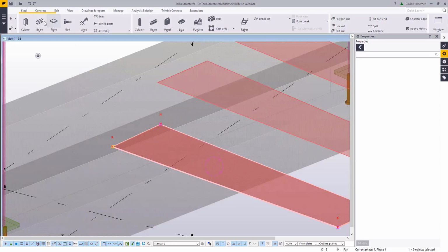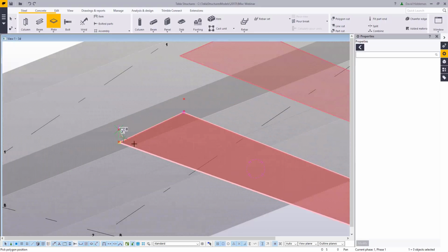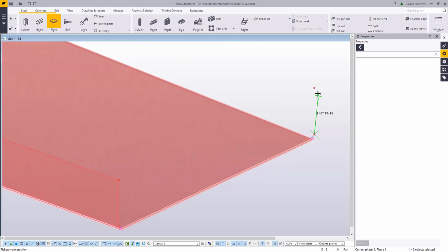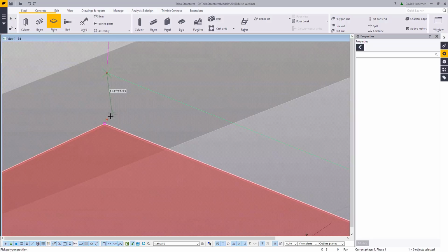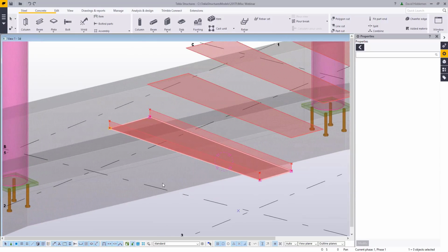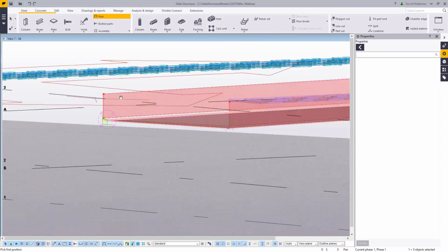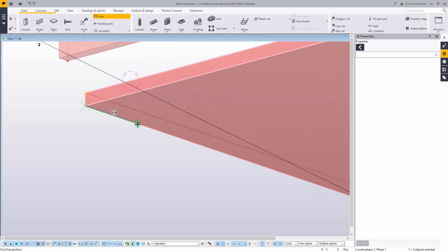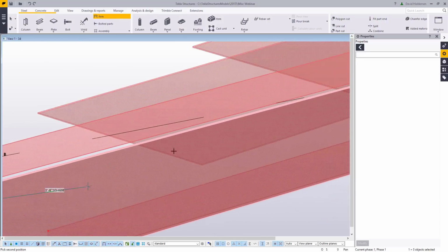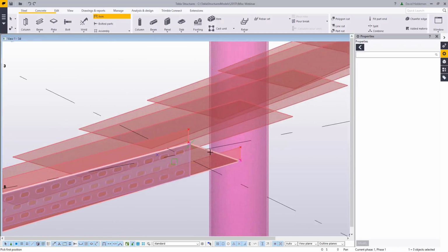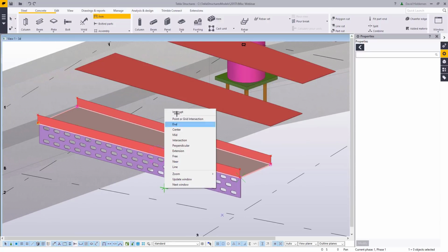I'm going to reuse the properties of that step to draw in the rest of my plate. Now, I cheated a little bit. I have some work points in here to help me out. Again, this is just for time's sake. Obviously, it would not be difficult for me to just do some offsets and create those again. But I have those edges of my pan created. I'm going to recreate that riser, and since it's curving upwards, I'm going to come back a 1/2 inch on one side. So let's go a 1/2 inch over, just track till we get to a 1/2. On the other side, we pan over a little bit, we'll come back a 1/4. And I would probably take a little bit more time to measure this out, as you can understand. But I've created now a custom step of sorts.